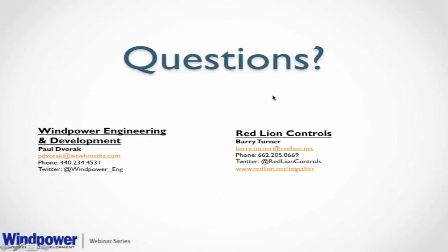So Ethernet doesn't have it natively, but protocols have been built on top of it that allow that. And Ethernet IP is just one example of many that make that happen. So we have plenty, tons and tons of people. Ethernet IP is the protocol that is used predominantly throughout the United States and a large part of the world. And that's what it does. It gives you a deterministic network. And so it changes the way that traditional TCP/IP works and adds things on top of it to make sure that it communicates successfully. And if a drive were to fail, then the PLC knows right away.